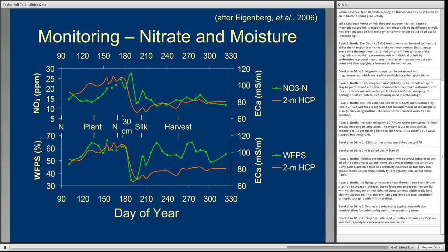To make sure that this wasn't a variable that I had to be worried about, or if it has a significant effect relative to other effects, you could implant some thermometers at reference points and look at how warm the soil is versus how conductive the soil is at those reference points that you go back to again and again and again.